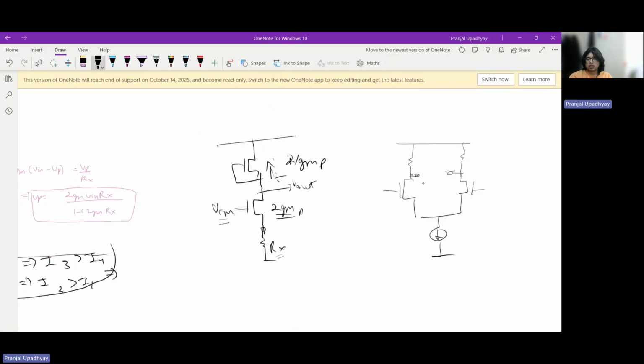But when there is some variation in the common mode signal and we are taking only the single-ended response, the common mode to differential conversion is there. I think we did not discuss it, but the main idea was that in a fully differential amplifier, the common mode to differential mode conversion was happening only in case of mismatch.